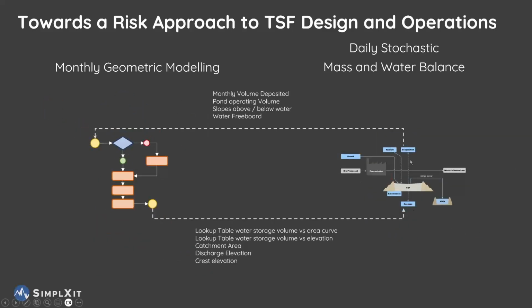The water balance runs its daily mass and water balance, and then at the end we get the monthly volume that's deposited, the pond operating volume, the slopes, and the water freeboard that's being fed into Muk3D. Muk3D then does its deposition runs, and ultimately calculates the lookup tables, the areas, and the discharge elevation, which is fed back into GoldSim.